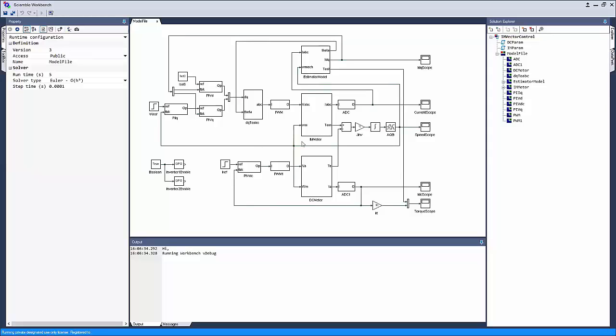In addition to the induction motor, on the bottom we have a DC motor because this is a coupled motor generator combination. In our simulation, we use just a step block to simulate a load condition, but in real time we need to have another motor coupled that can emulate a load. So we have a DC motor that is being run in torque control, or since in a DC motor the torque is proportional to the armature current, we are running this in current control, and we are applying a load step in the current, which in turn translates to a load step in the torque.